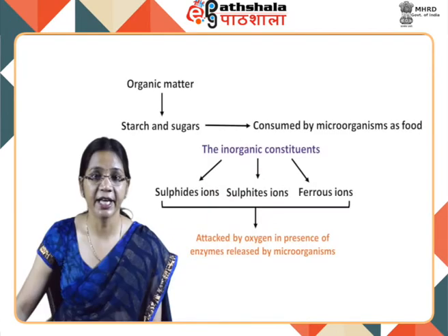Biochemical oxygen demand or BOD is a standard measure of the amount of oxygen that would be needed by the microorganism to cause biodegradation of a part of organic and inorganic pollution load. The organic matter like starch and sugars are consumed by microorganism as food.